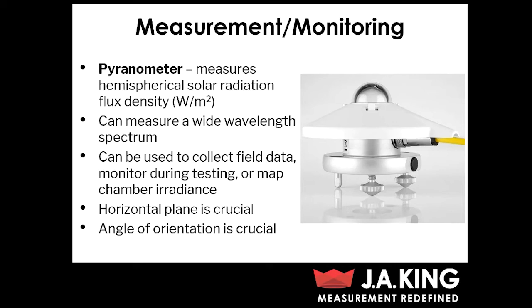And pyranometers can be used both to collect field data. So if, for instance, you don't want to use those irradiance maps or you want something a little bit more accurate, you can actually take a pyranometer, set it outside where your parts are going to be used, and collect some field data. And you can also use a pyranometer during the actual test itself to help monitor the test and make sure you're hitting the values that you want to hit.